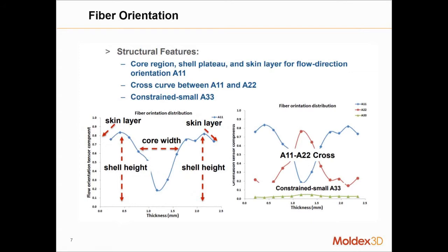So you can almost think of it like a stick in a stream. The stick is going to apply as much surface area resistance to move along the stream as it possibly can, so it's going to turn sideways. And the fibers will do exactly the same thing. Those fibers are turning sideways and being pushed along the flow path with the polymer. And that's why we end up getting a very low fiber orientation in the core.